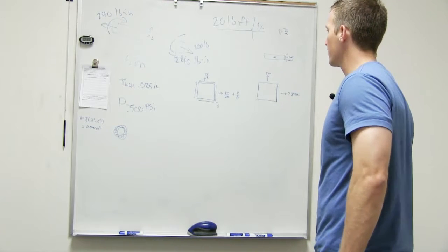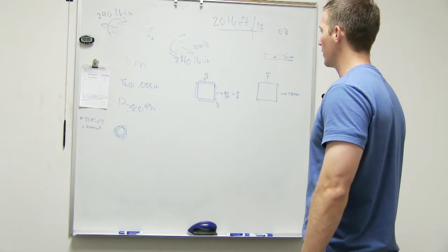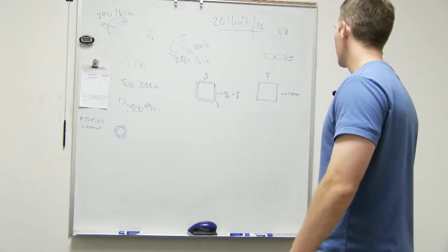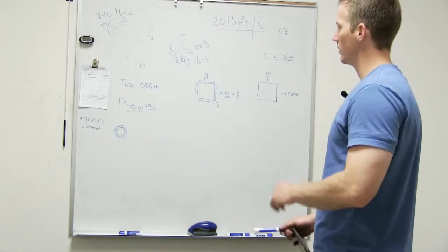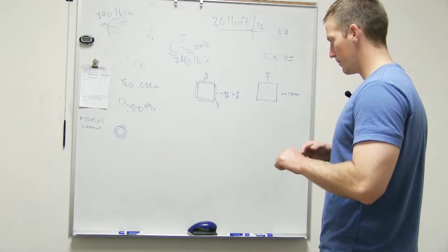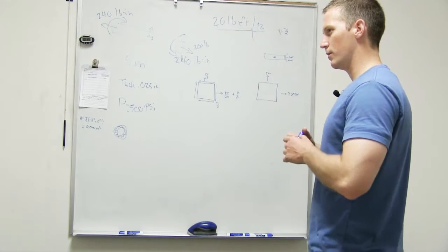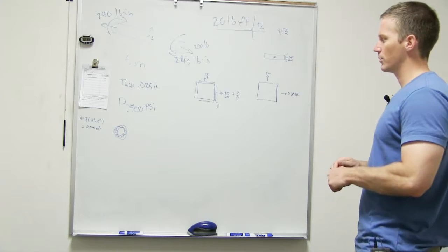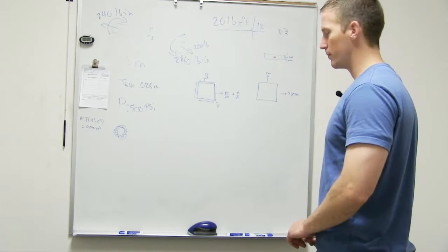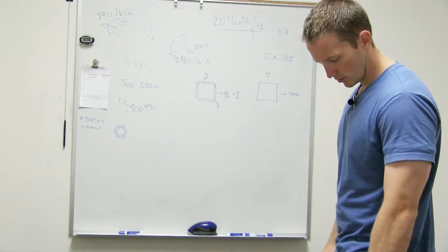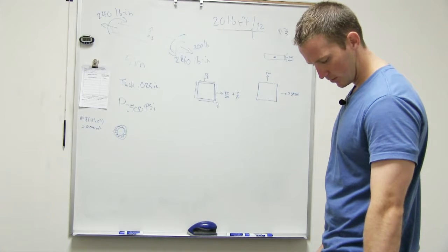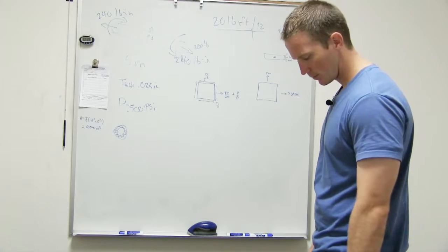Awesome. And then we need to figure out what our TC over J is. Did you add on the P over A? Yeah, P over A. We're doing the 200 pounds for that one, right? So the 200 divided by our 0.041. So that's 4,878 PSI. Okay, awesome. When you add them together, you should get that number, which is equal to 7,378 PSI.